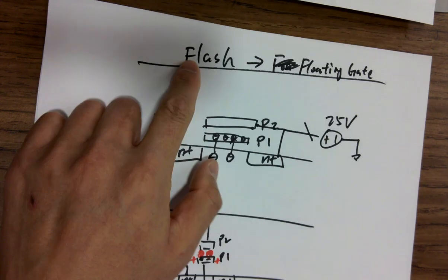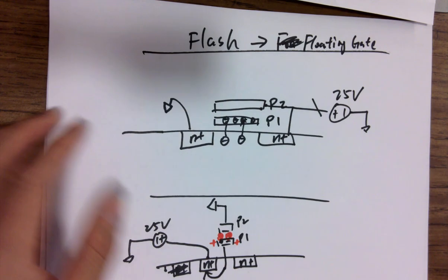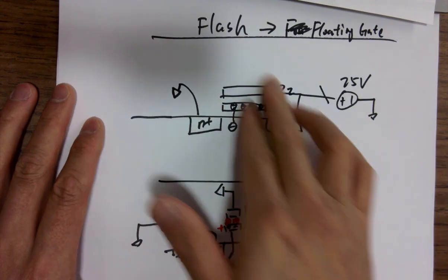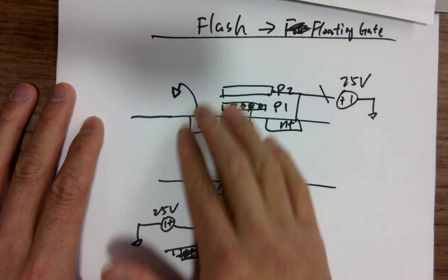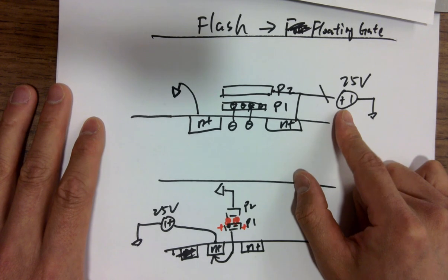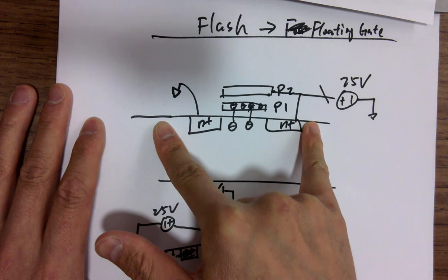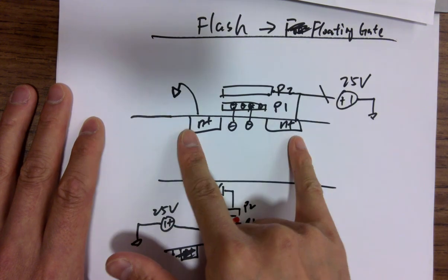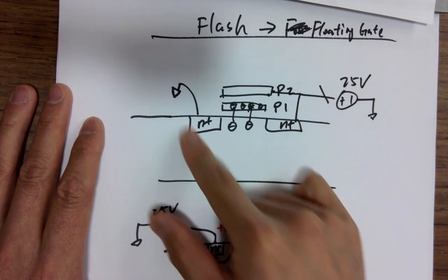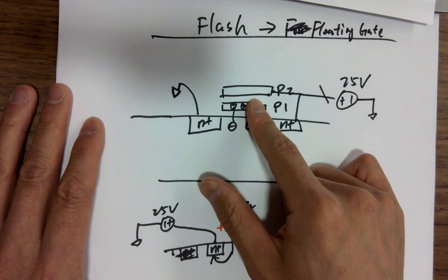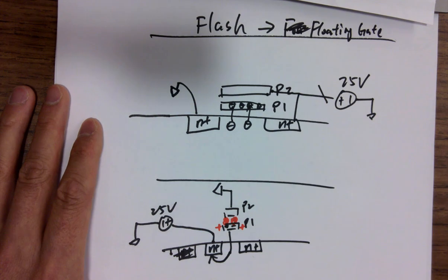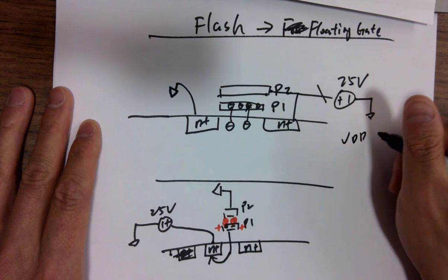So flash is more modern, and you can read and write to it, but it's more expensive because these are special structures. It's larger in size. And why larger in size? Because you are applying a big voltage. The big voltage requires a larger size, otherwise it will be burned, right? It will be damaged. So it's able to handle the larger voltage, so that's why it's big. It's large transistors, and it also requires a voltage higher than regular VDDs. VDD is usually 5 volts for the USB.